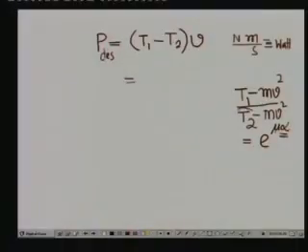So, normally for all situations, the smaller pulley is the guiding pulley. That means all the designs are based on the smaller pulley, because the power transmission capacity on the smaller pulley will be smaller than what you will obtain if you consider the larger pulley. So, you understand that the guiding feature will be e to the power mu alpha for the smaller pulley, and the value of mu alpha should be expressed in radians, that you should keep in your mind. Well, so from this equation you can get the value of T.